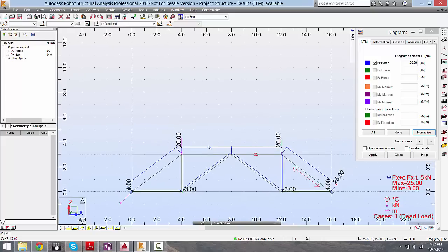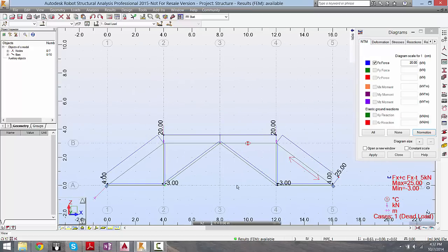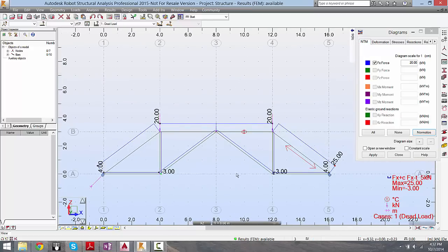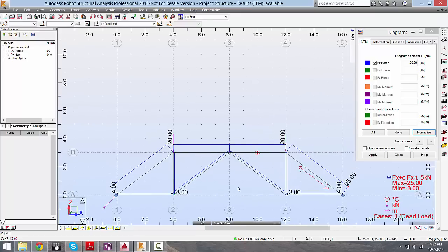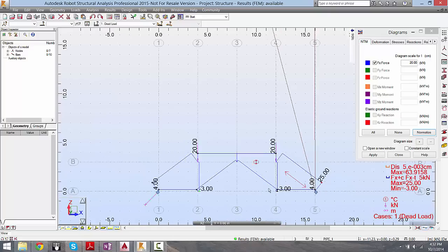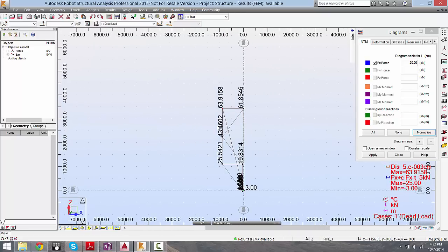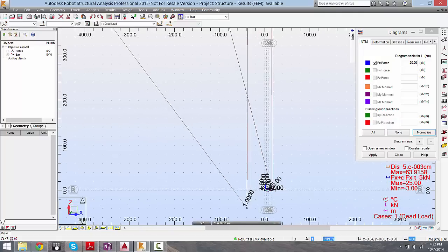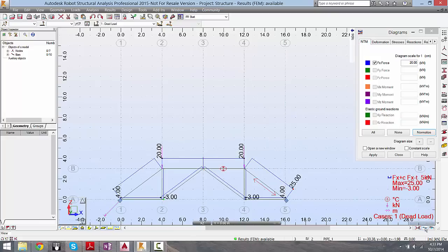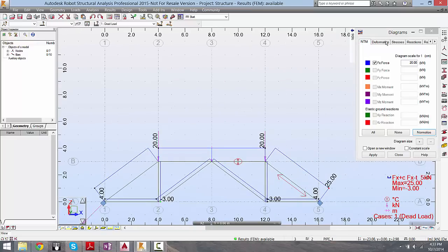One thing to remember is that for statically determinate structures, any initial imperfections or thermal loads or anything like that will not cause an increase in forces in the bars. However, if we were to look at the deflection, it went crazy. It's all over the place. It's pretty much sideways where everyone's dead. Everyone is dead. Yeah, all the deflections changed, but the forces in the bars have not because the truss is determinate.